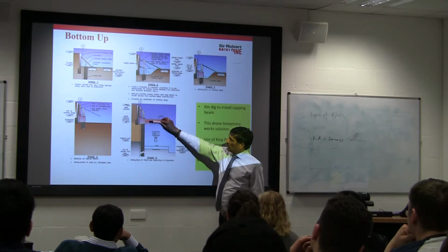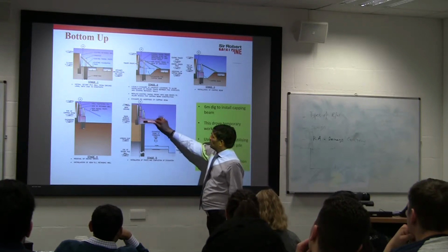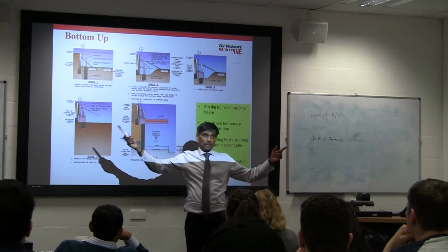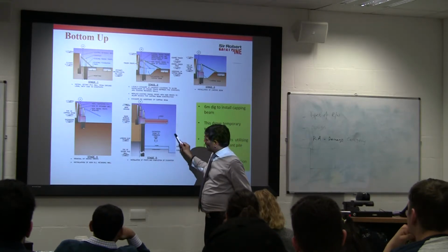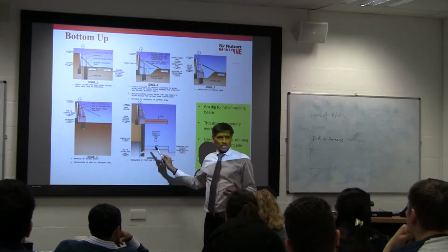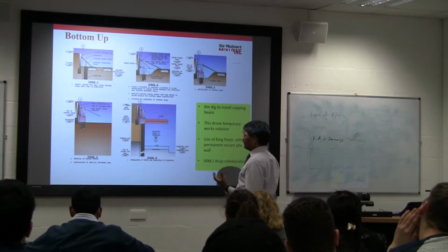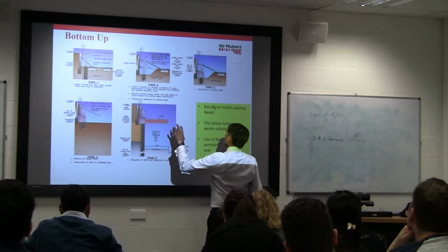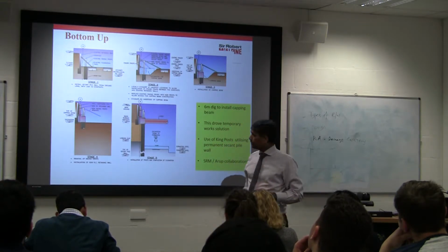This prop, is it a fly-through or a raking prop? It's a fly-through, yeah? This is a fly-through. So this is actually going from one end of the building to the other end of the building. So the beauty of this is again the amount of volume that you are getting here, the amount of space that you are getting, the amount of logistics that you can do within that site is really amazing, and that is where health and safety of the whole personnel working on site is improved dramatically.